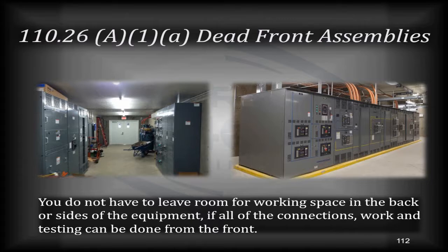110.26(A)(1)(a), dead front assemblies. You don't have to leave any room for working space in the back or the sides of the equipment if all the connections and the work and testing can be done from the front of the equipment.